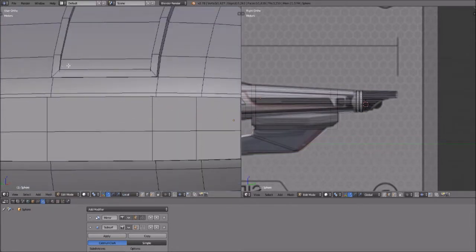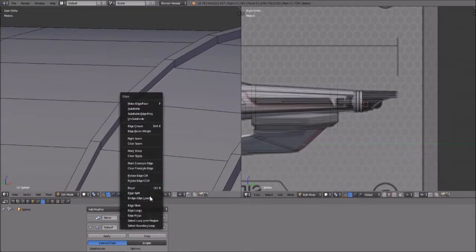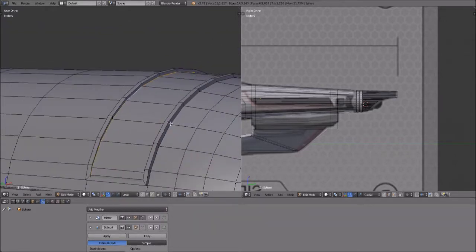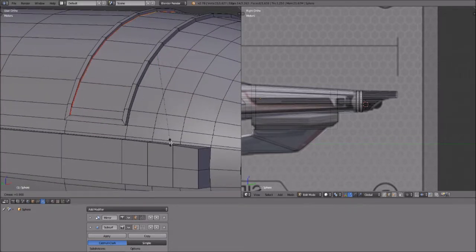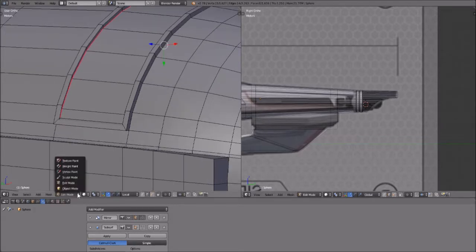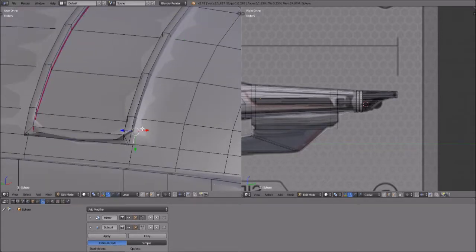Like in this area here, if I find an edge loop that I want, like this one right here, press Control E and select that whole edge loop, then do a Shift E. Let me move over here where we're actually working. I can increase that edge. We'll be able to see it better on this outside edge. So again, if I select, Control E, select that whole edge loop, and then do a Shift E, I can increase that seam and make it a lot sharper.